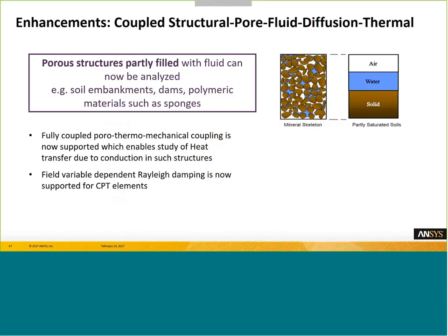Also, we've expanded our capability on structural-pore-fluid models. So this is porous structures such as soils or sands, and we've now got the ability to have a mixture of materials. So we have the solid, air or voids, and then also water, so that we can have partly saturated soils modeled more accurately. So we can now also do fully coupled poro-thermomechanical, which allows us to model the heat transfer